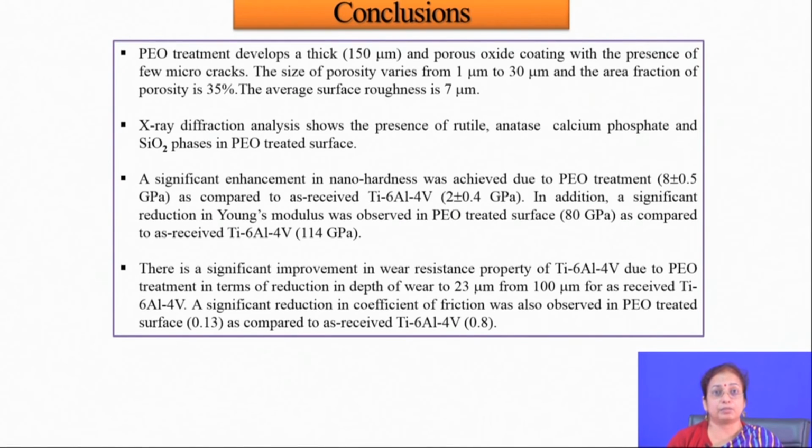There is presence of molten or solidified aluminum in the channel, which actually offers toughness to the surface or oxide layer. It is basically a kind of cermet layer which forms on the surface of the metal.